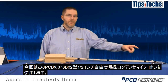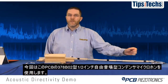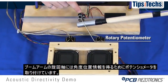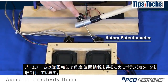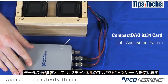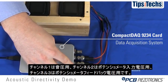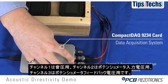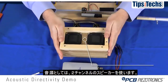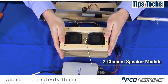Here we have a PCB Model 378B02 half-inch free field condenser microphone that's fixed to a rotating boom arm. The boom arm is pivoted around a rotary potentiometer, and that provides the angular position feedback for the directivity measurement. For our data acquisition system, we're using a compact DAQ chassis with 3 channels of data. The first is the sound pressure, the second is the potentiometer input voltage, and the third is the potentiometer feedback voltage. Finally, we're using a 2-channel speaker module as our source.